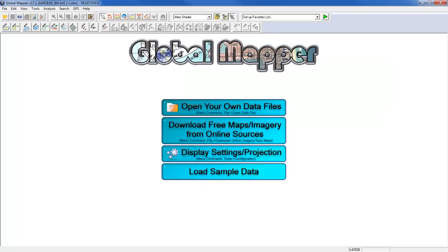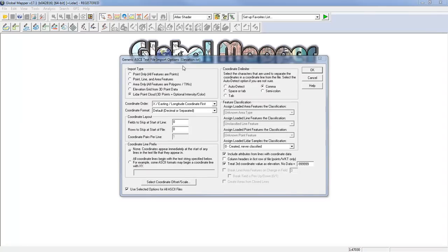I'm going to close the file, and off screen again, I'm going to quickly drag the file that we were just looking at onto my map. We could go to the file menu and initiate the import from there, but dragging and dropping is often the most straightforward way. Now, in this dialog box, we're being prompted to apply the parameters of that file. We do have a few options in here that allow us to immediately create an elevation grid from this data. I typically don't recommend that approach because I often find it valuable to see what the point distribution is like before actually rendering that. So we're going to bypass that. Although it is an option, we're going to simply display the points on the map. From there, we can manually go through the process for creating a surface.